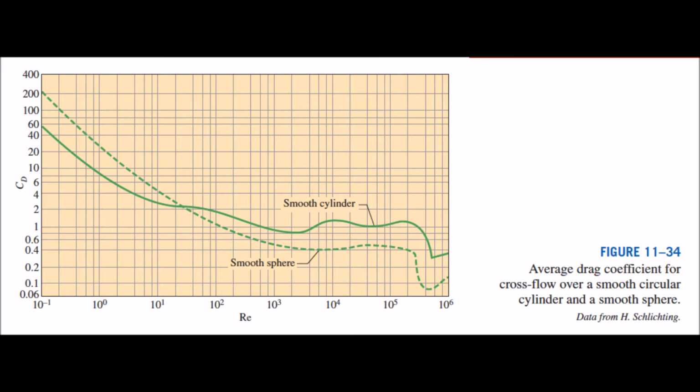From this figure, one can deduce that the coefficient of drag should generally go down with increasing Reynolds number, although this does not mean that drag force will go down with an increase of Reynolds number.